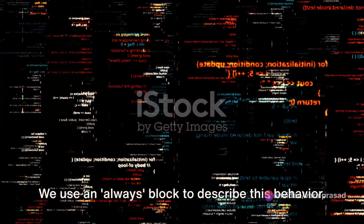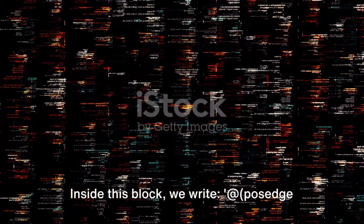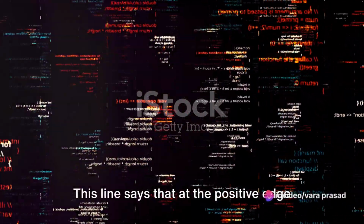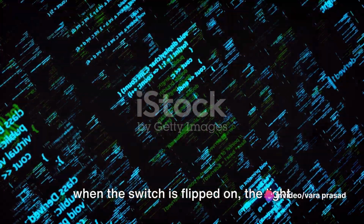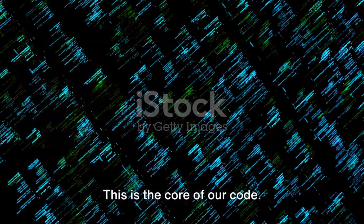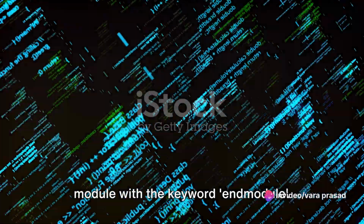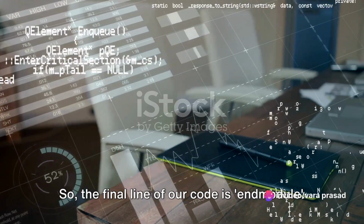We use an always block to describe this behavior. Inside this block, we write posedge switch, light equals sign tilde light. This line says that at the positive edge of the switch, that is, when the switch is flipped on, the light should change to the opposite of its current state. This is the core of our code. But before we finish, we need to end our module with the keyword endmodule. So the final line of our code is endmodule.